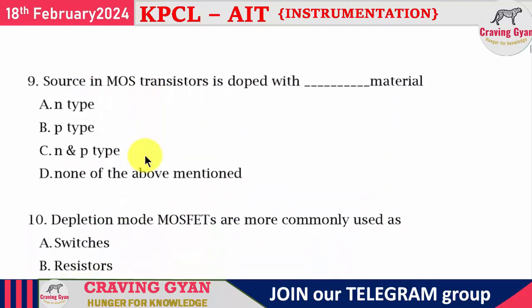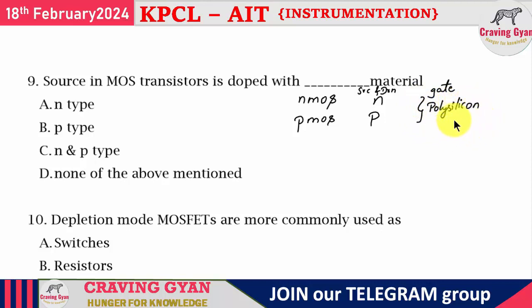Ninth question, source in the case of MOS transistor is doped with. See, in the case of NMOS, the source terminal and the drain terminal is made up of N type. And in the case of PMOS, the source and drain terminal is made up of P type. Now, if I am speaking with respect to the gate terminal, in both the cases we are going to make use of polysilicon only.